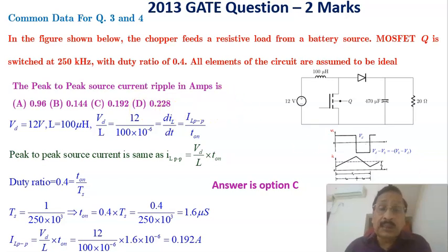As the solution, first, this is a step up chopper, and the input voltage is equal to 12 volts. The input side inductor value is given as 100 microhenry, and the source voltage is 12 volts. The MOSFET is triggered at 250 kilohertz, and the diode and capacitor values as well as the resistance values are given. Now when the switch is on, the MOSFET is on, this inductor is directly across the source.